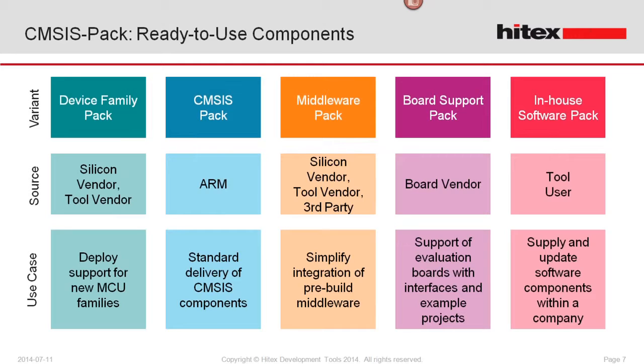Aside from supporting the microcontrollers directly, software packs can also be used to transfer raw middleware or board support packages as well. So again, if you're developing a board that you're going to give to third parties, you can make a supporting pack, or you can develop a standard library and bundle that up as a pack as well.